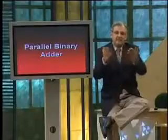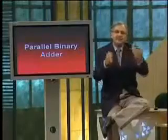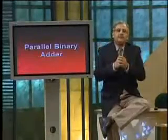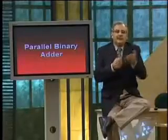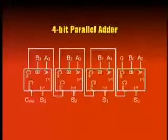Similarly, the carry out of the second full adder is connected to the carry in of the third full adder, and similarly the carry out of the third full adder is connected to the carry in of the fourth full adder. So in this manner, by connecting 4 different full adders together, you can implement a 4-bit parallel adder circuit. Let us have a look at the 4-bit parallel adder circuit. The least significant full adder, which adds bits A0 and B0, is shown on the right. The sum output is, of course, S0. The carry in to this full adder is connected to 0 because there is no carry in to this particular full adder.